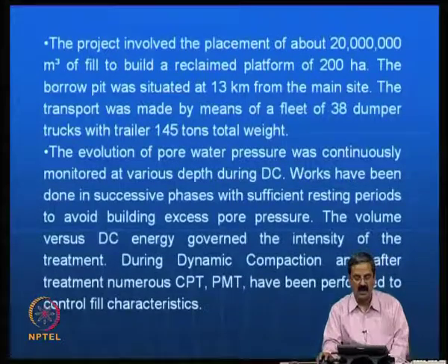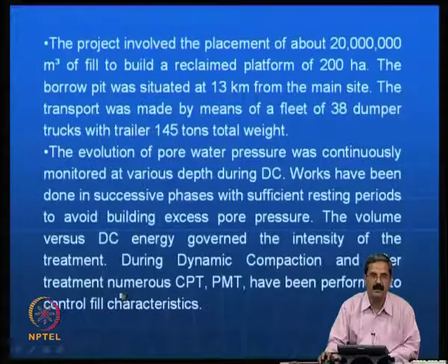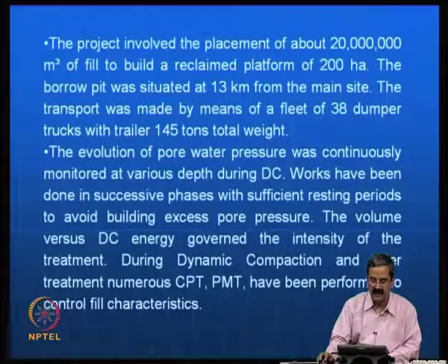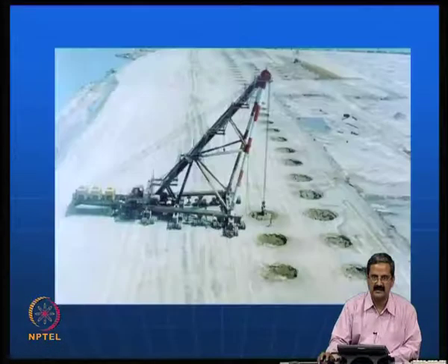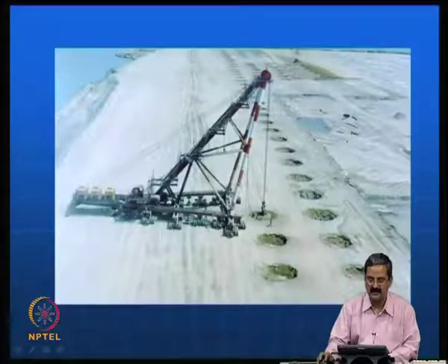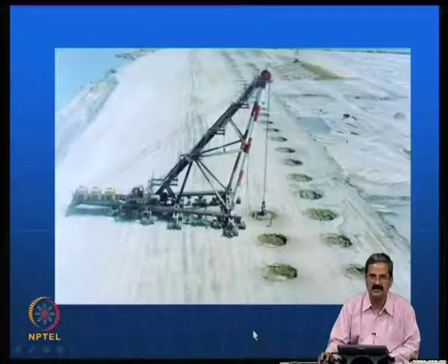So for example, how much is the volume that has been compacted, and the energy input into the system is something that is very important, and they were able to understand this process. And during the dynamic compaction after the treatment, they have done a number of CPT tests, pressure meter tests to control the fill characteristics. You can see that this is the process of compacting, you can just see that they have a specific sequence here.